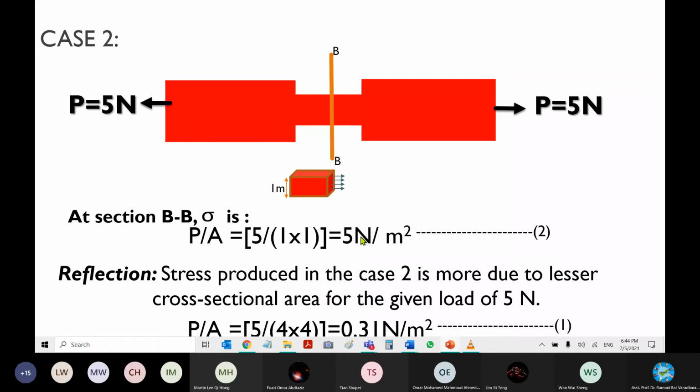When it is pulled and the cross section reduces, the value of stress changes to very high, isn't it? Now you understand the effect due to cross section. As the cross section decreases, the stress distribution will be intense, very high, isn't it? Having understood this, you should try to avoid the thinning effect, I mean the necking effect.